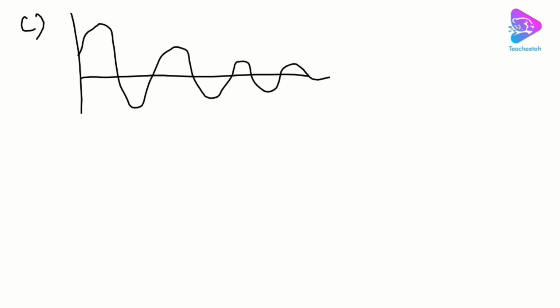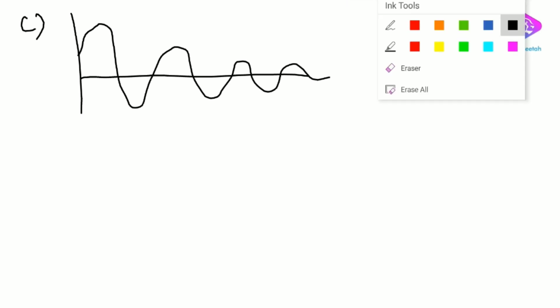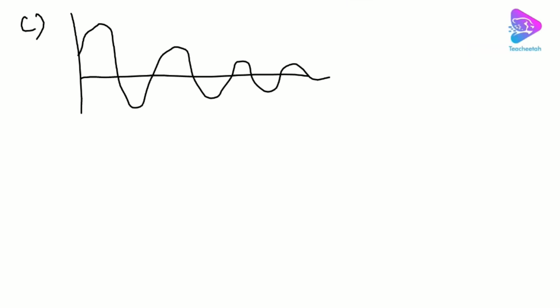So let's first define what the logarithmic decrement means. Again, I want to plot an arbitrary response of an underdamped system, which is like this. If we look at the slope, or how the amplitudes are decaying, it is like an exponential decay. In fact, this curve follows e to the minus zeta omega n t, and this part is the harmonic part, or the cos and sine function combination.